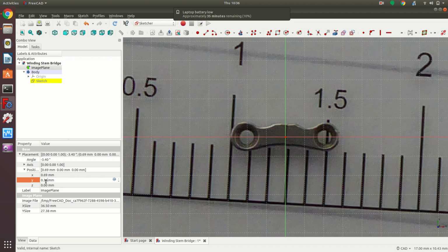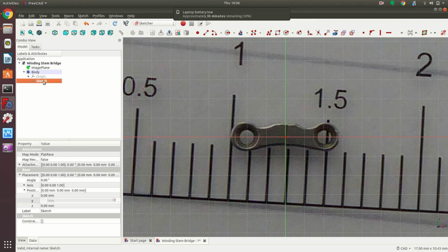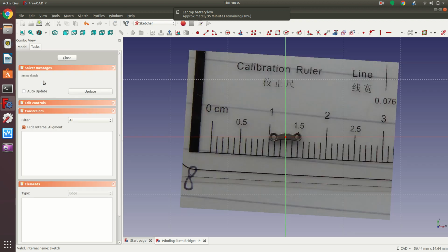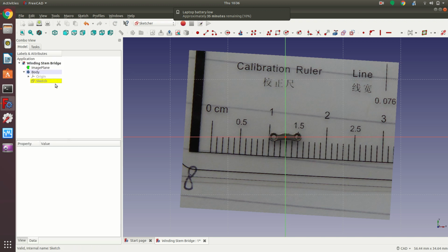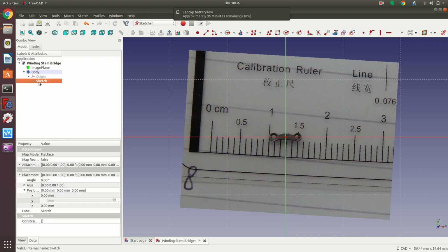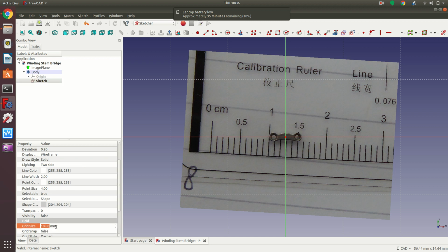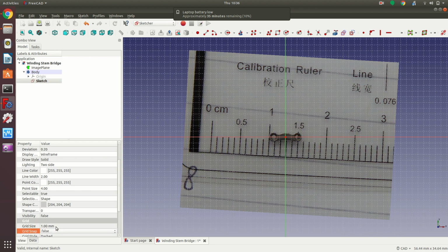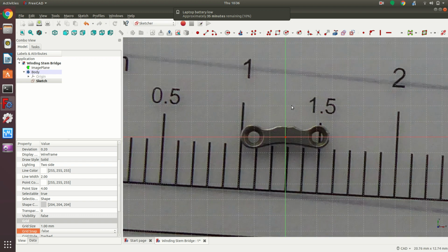Yeah, that holds, the whole center sits on the x-axis. I think that's pretty much there. And now we go back to the sketch design. As you see, sometimes this thing loses the grid. We now have a 10 mil grid. We don't have a 1 mil grid anymore. It just does that sometimes. No problem. You go back to the view and you just say, look, I really want that 1 mil grid again. And we're there. Now Control Plus gets us in, a bit out.